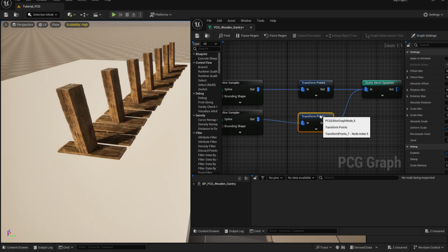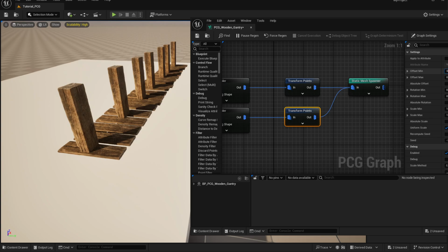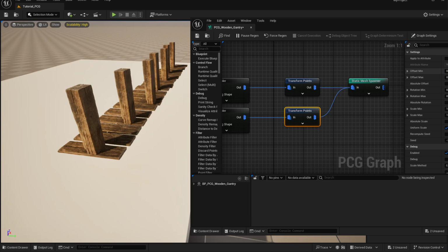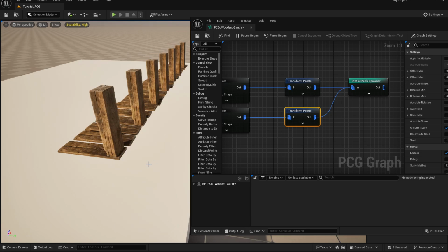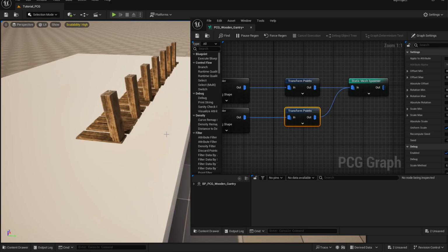There we are. And all we need to do really to make this work is a little bit of scaling, and we also need to do a little bit of offsetting, yeah? So again, it's going to be a case of finding which offset we need, and the offset is going to be on the Y, 35, do it again here, 35. So you'll notice if I do it at 35, it comes pretty much all the way at the edge. Some are overlapping, some are not, because of the nature of what it is we've just done. We also need to rotate it. Now, last time I believe we rotated it on the X.